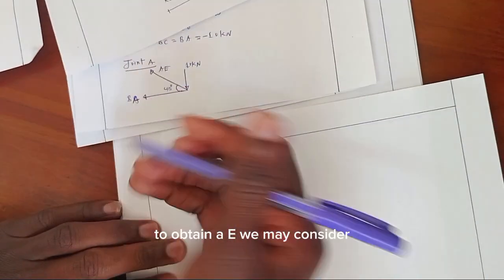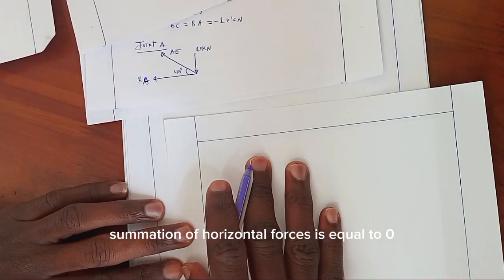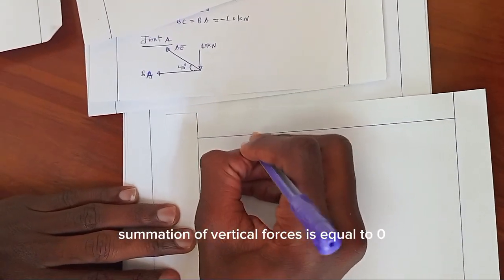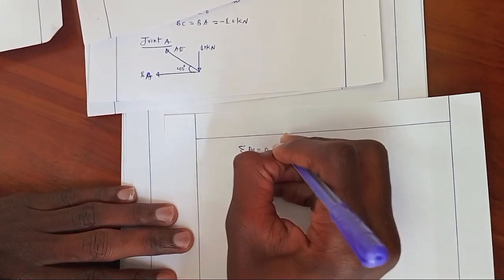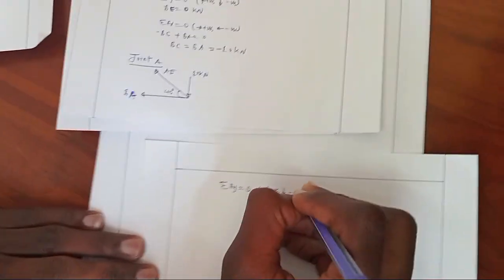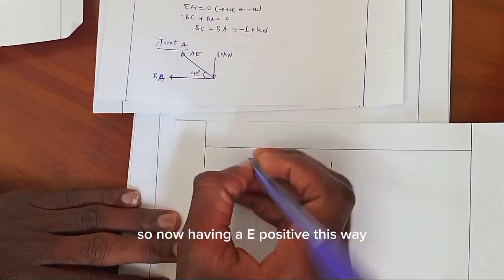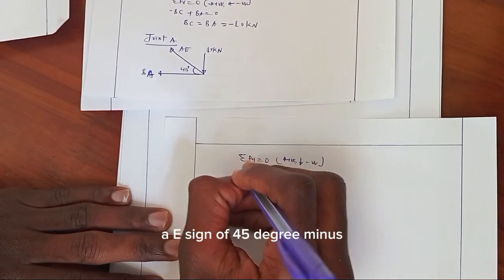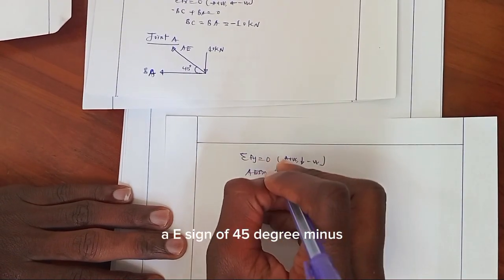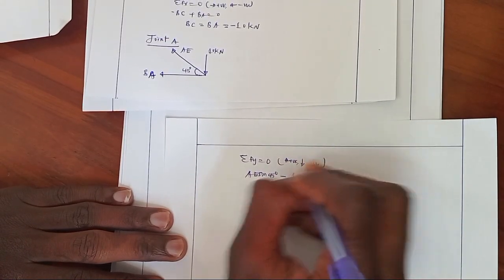To obtain AE, we may consider summation of horizontal forces equal to 0 or summation of vertical forces equal to 0. Let's consider summation of vertical force is equal to 0. Positive upward, negative downward. So now having AE positive this way, AE sine of 45 degrees minus 10 kilonewton is equal to 0.